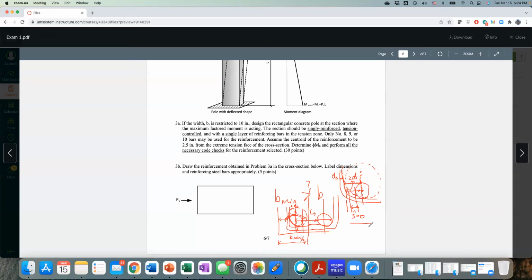Alexander, does that answer your question? Partially, yes. My concern was mainly with getting the whole b minimum, given there's at least another bar that we have to go across to get the minimum. Like if there's, say, 5 bars singly reinforced, then it stretches beyond just 1, so it's not just the 2ds, but then.